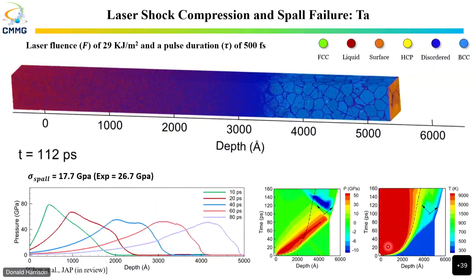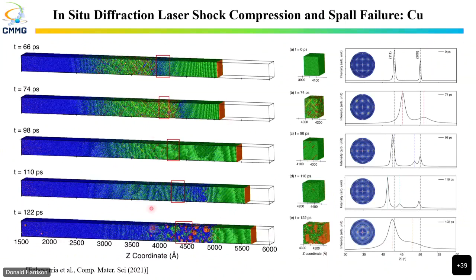The next thing is you can use this to generate diffraction patterns of the same systems over here. Again, we are taking small sections for these systems because of the computational cost associated with it. But it allows us to look at selected area diffraction patterns or these intensity profiles, and you can start correlating the role of microstructure on the shifts of the peak or the broadening of the peak. One of our current efforts is to come up with ways to combine diffraction patterns from different sections of the sample that allows us to recreate the whole diffraction pattern. So you'll have a liquid phase and ablated phase and everything, and see how that correlates to a full diffraction pattern as well.